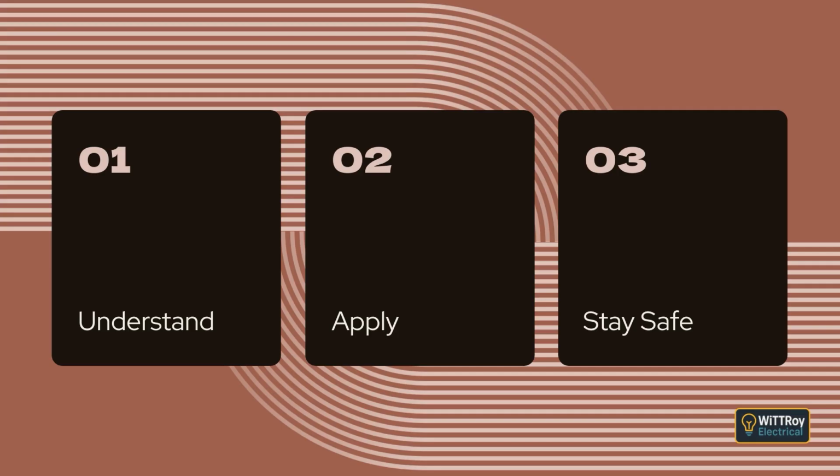Clause 3.7.4 Installation couplers. Installation couplers may be used for connecting cables, including flexible cords and rigid conductors, as long as they comply with NZS 61535. These couplers are designed for permanent connection and must be used correctly. Some require deliberate action to disconnect, and they must not be engaged or disengaged under load unless designed for that purpose.